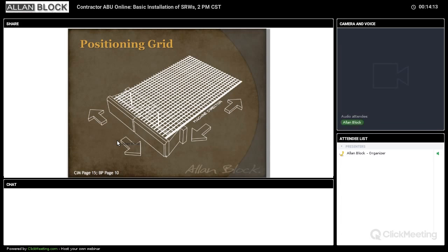So you need to put that grid in perpendicular to the wall face. If you put it in incorrectly and you rotate it around and you roll that along the wall and you're using a uniaxial grid, you could have grid strength in the direction of the force about half as strong as the strong one. So you really need to know what kind of grid you're using and how to put it in correctly.